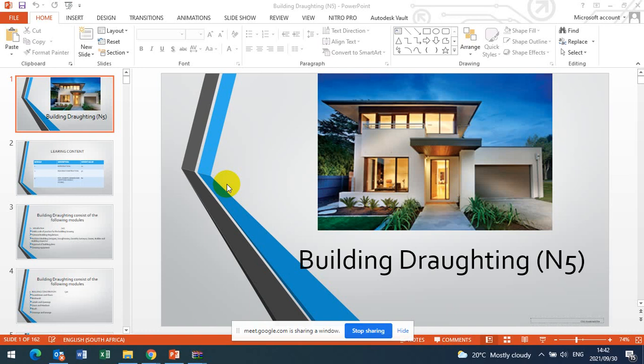And on your floor plan, there must be a true geographical north in relation to the location where the dwelling is based, because the north can change depending on where you are on the earth. Yes, we call it the true north. True north, correct. So that true north tells us exactly which side is our north elevation, and then we will know that the opposite is our south elevation, and then there will be east and then west.